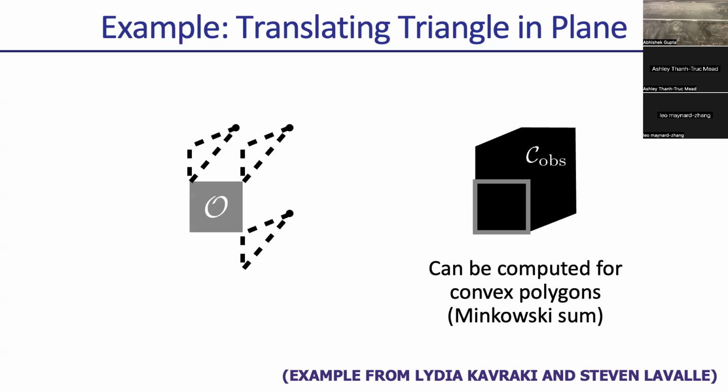What that means is that in the configuration space of the robot, if the robot is at any of these points, it will be in collision with the obstacle. Does that make sense? The important thing is that the obstacle, which was a square in the world space, is not a square in the configuration space. So the transformation of seemingly simple obstacles in world space into configuration space gets kind of nasty.